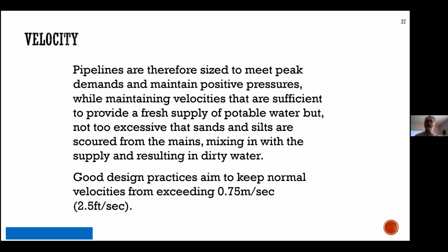So the engineers in, say, Whistler, where the Olympics were held, have a different challenge to meet the system design. And think about designing a system where resorts have this issue where they may go up to 10,000 people, and the rest of the year, 8 months of the year, there's 2,000 people. Well, that means you've got much larger pipe or much larger reservoirs in order to meet those 4 months of the year versus 8 months. So that means, okay, we've got different issues. Maybe we have issues around water getting stale or not enough flow.